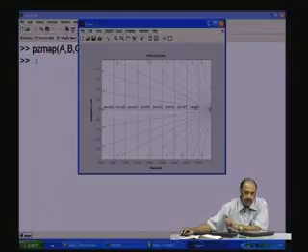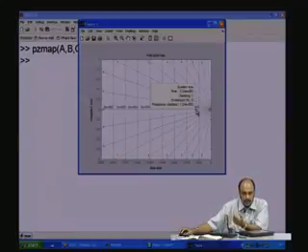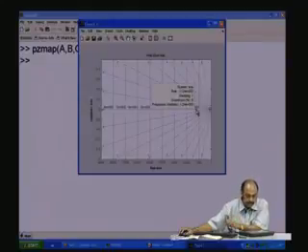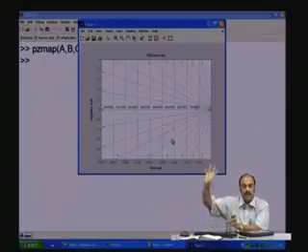Let us see what happens when we take the second case, when the output resistance, that is R2, is made larger. Which means there are now some oscillations which are going to occur between the capacitance and the inductor. It is now going to act more and more like a resonant tank. That is, when R2 becomes totally open circuit, it is just pure LC, because R is just 1 ohm. So, it is an LC tank, and therefore, it will start oscillating more and more. Which means these poles will start moving up and below. So, you will have one pole here and one pole here, and they will start moving towards the imaginary axis more and more as you make R2 higher and higher.